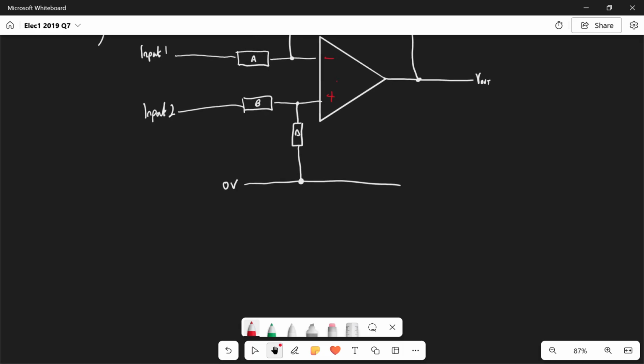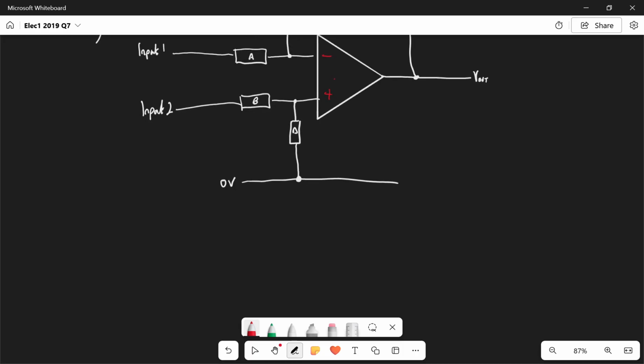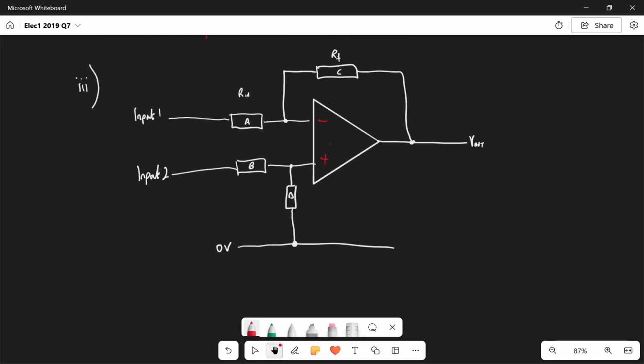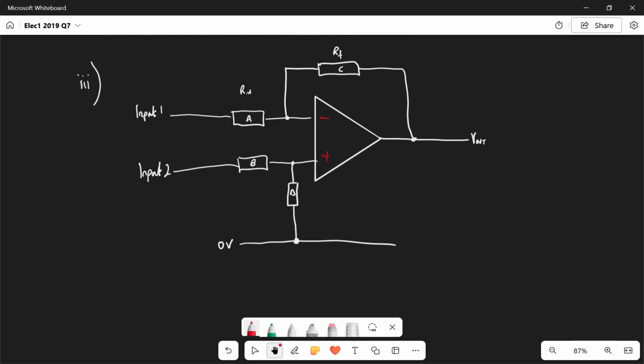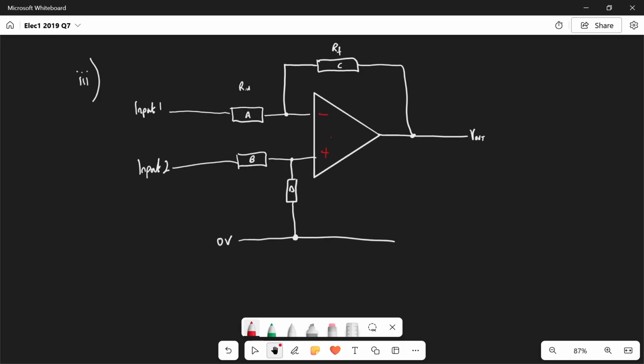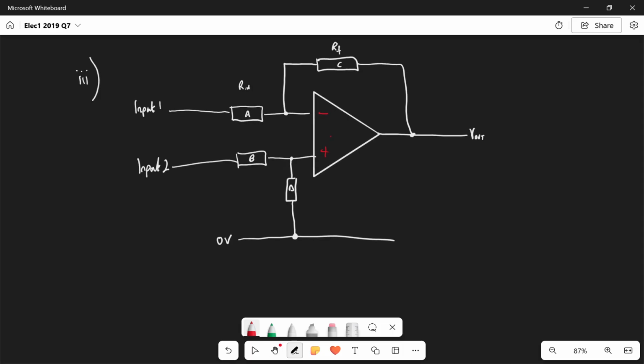Well, we're going to use the information there of, when the temperature sensing unit's output voltage Vout is minus 0.3 volts and the output of the difference amplifier needs to be 9 volts. Well, that means Vout is 9 volts and the difference into the difference amplifier is minus 0.3, and that is the voltage going into input 1.